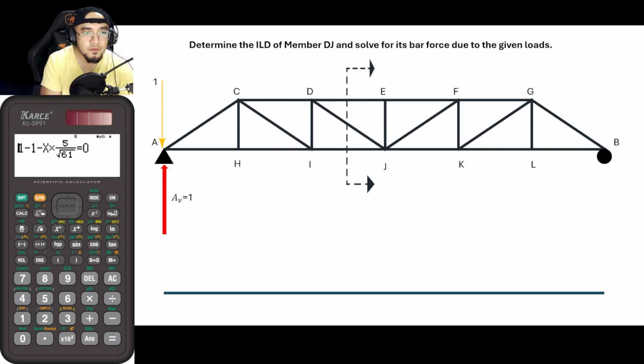So from that, for the first point, we would now be assigning a certain point at this part. Okay? So next up, you could actually move this to the next node, then after that, to the next node, up until once again you reach the last node. But rather as a shortcut, since our bar force is located here at this point, let us move this load to this joint here, which is aligned to this particular node.